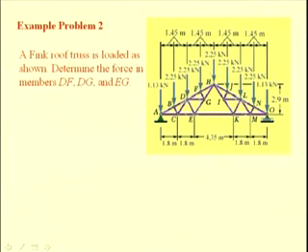And we are interested in finding the forces in the members DF, DG and EG. In order to determine these forces, we can conveniently use the method of sections.